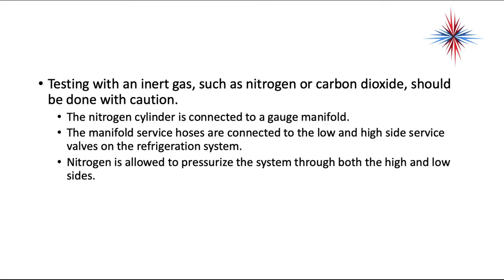Testing with an inert gas such as nitrogen or carbon dioxide needs to be done with caution. The nitrogen cylinder is connected to the gauge manifold, and the manifold service hoses are connected to the low and high side service valves on the system.